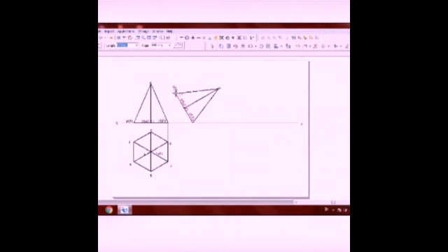Now draw the projection lines from that front view downwards. These three lines represent the base. Similarly, corresponding horizontal lines for constructing the base are to be drawn. Yeah, for the axis and the apex, a longer one. Next, for the base edges. And the final line. Of course, these are construction lines and therefore must be very thin lines. There is a small gap there, and therefore go to extend and extend it.